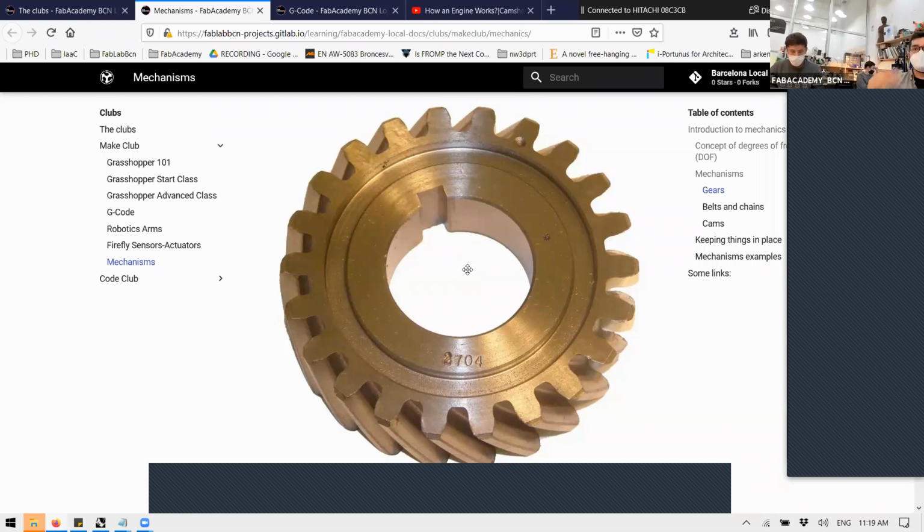With helical gears the contact happens slowly: you start touching a little bit, it increases, and then it decreases. So that actually produces lower power losses compared to a straight touch.